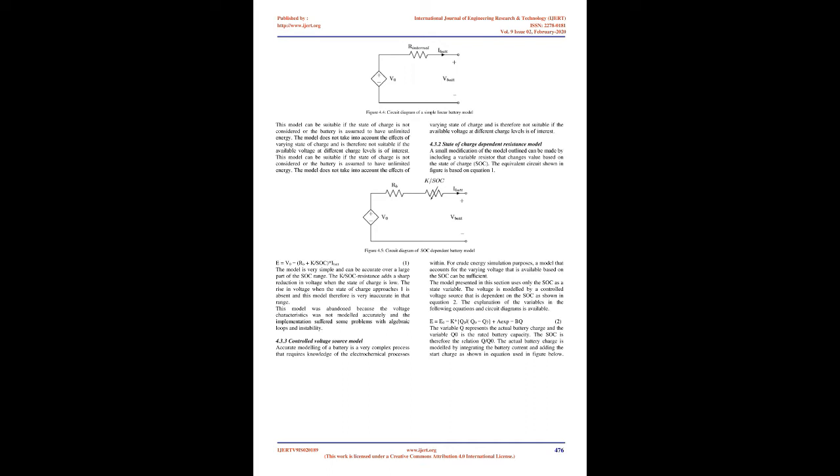Inverter. The inverter allows transforming the DC current to AC. A photovoltaic installation that incorporates an inverter can belong to two different situations, based on the characteristics of the alternating network. In the first, an isolated system, the inverter is the element of the network and has to feed the set of loads. In the second situation, the inverter is connected to the public network, to which it sends the energy generated by the system.